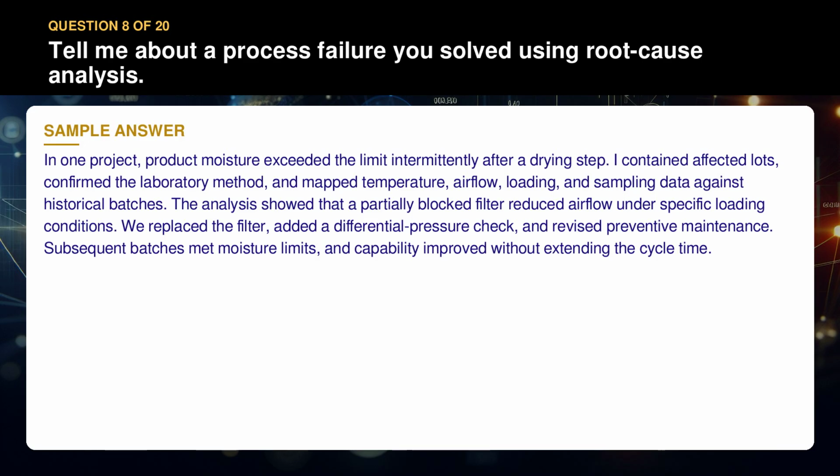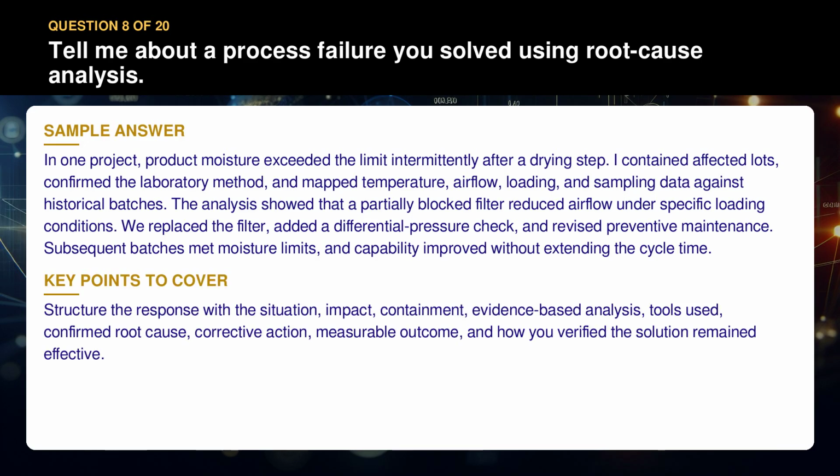We replaced the filter, added a differential pressure check, and revised preventive maintenance. Subsequent batches met moisture limits, and capability improved without extending the cycle time. Structure the response with the situation, impact, containment, evidence-based analysis, tools used, confirmed root cause, corrective action, measurable outcome, and how you verified the solution remained effective.